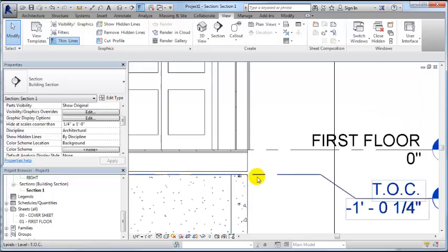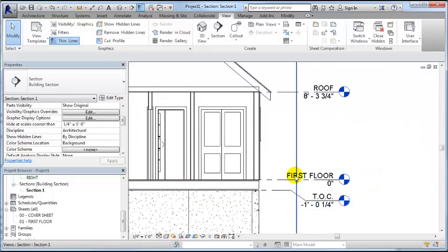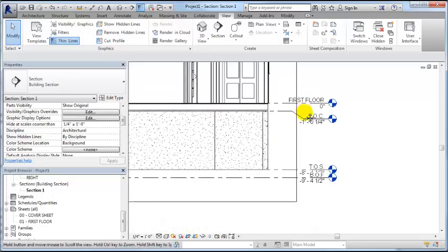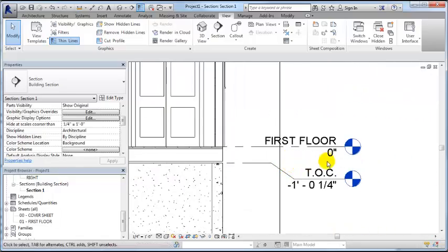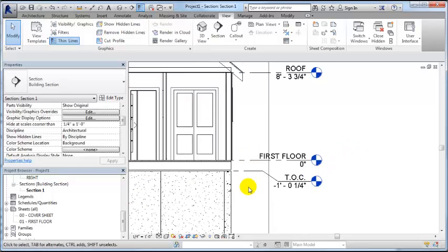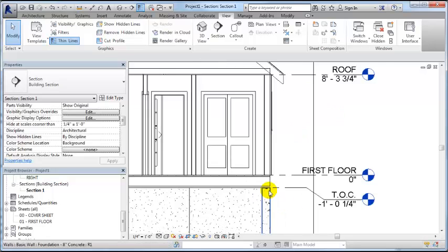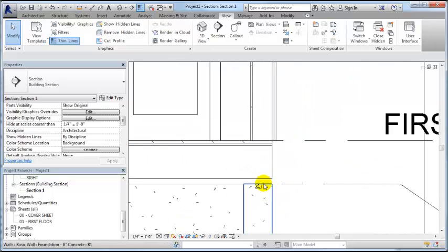That's the correct gap, and the fact that we could make those changes and not ruin our model is really important because we attached our walls to the proper levels, and so those changes were able to be made. And I wanted to make sure I did this on purpose so that you would see how important it is to have these walls and these levels attached so that you can make those changes on the fly. So now we have just the right amount of room here.